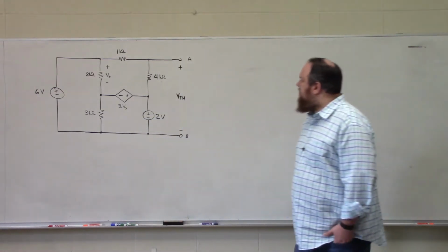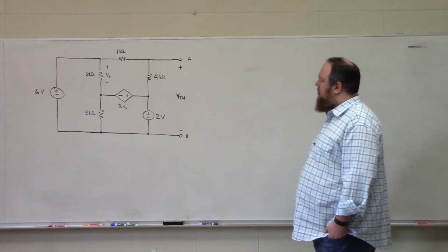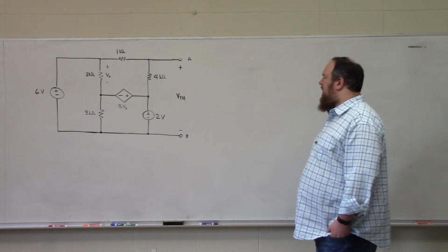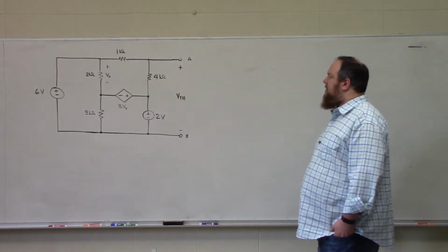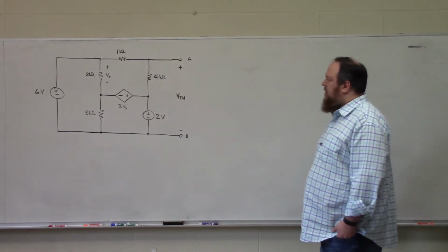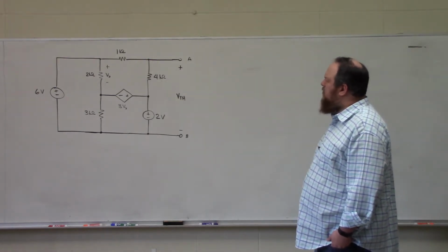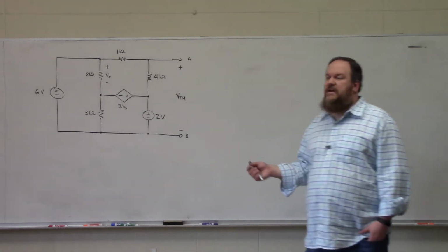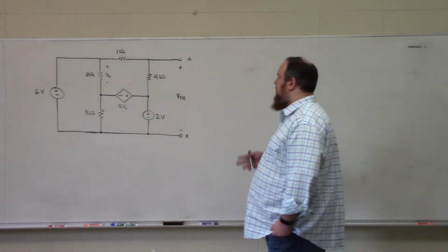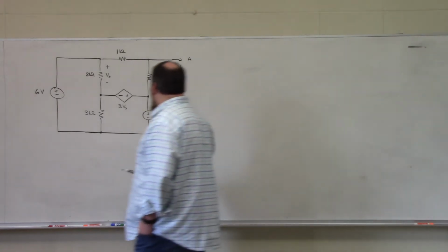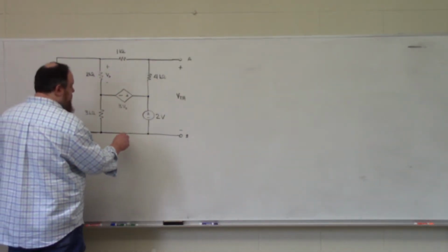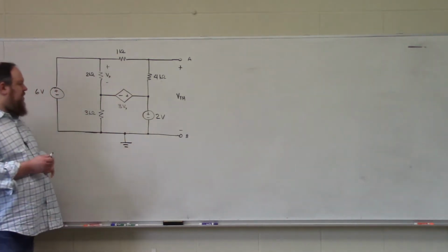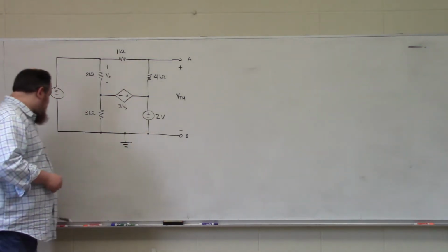There are a multitude of different ways that we could approach this problem. I'm going to choose to use nodal analysis, because I've worked this circuit multiple times and made the observation that nodal analysis is actually going to be much easier. You could absolutely do this using mesh analysis or any other circuit analysis technique, but nodal analysis gives us a couple of interesting observations. I'm choosing the bottom node, node B, to be my reference.